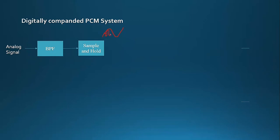The sampling that is used here is the flat top sampling, wherein the top of our amplitude is flat. It is not a natural sampling wherein the original form of the amplitude is retained. So again, what is used here is the flat top sampling. The output of our sample and hold circuit is actually a PAM signal.